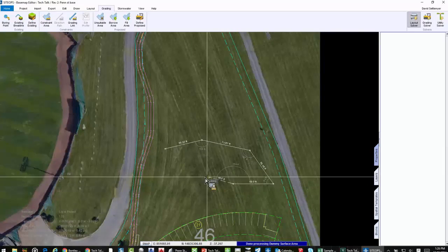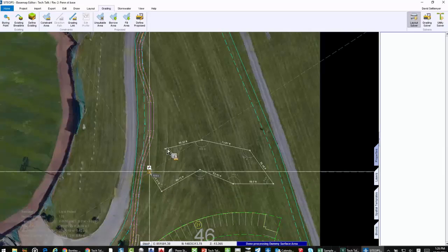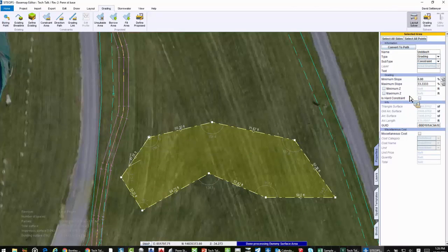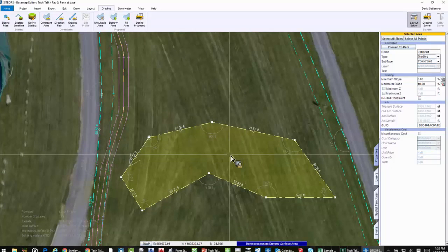It can be big, it can be small, it can be any direction, it can be anything we want. And it can sit over the top of an area. It can sit over the top of a parking lot, off to the side of a building where it covers the building and the sidewalk. Again, it lets me start grading and controlling things a certain way. So let's say all I want is anywhere in that area to grade at 10%. So I can do this.